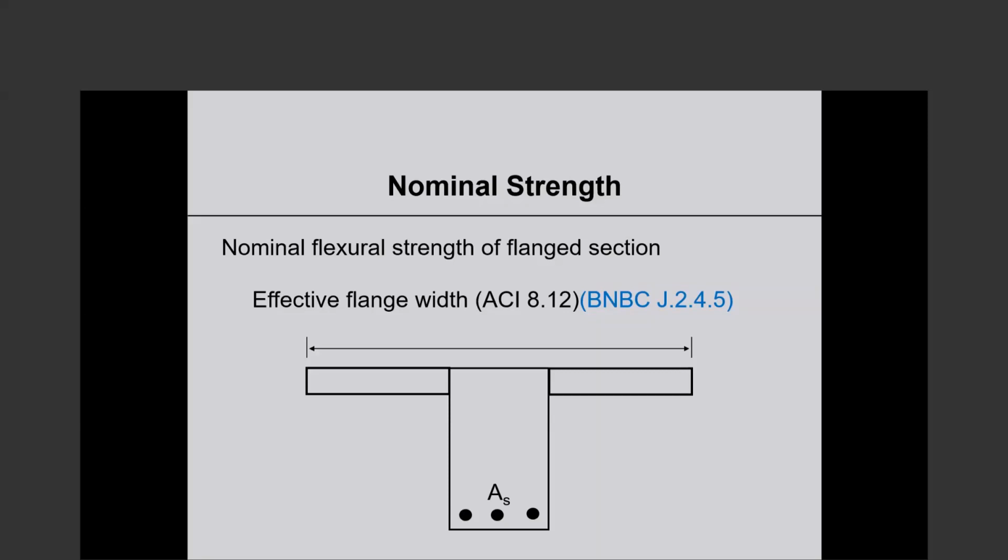Okay, so when you apply loads on this beam, the part of the slab on both sides act like flanges of that beam. Those also bend under load, just as the top portions of the beam go into compression. The flange portions close to the beam also go into compression. They effectively become part of the beam.